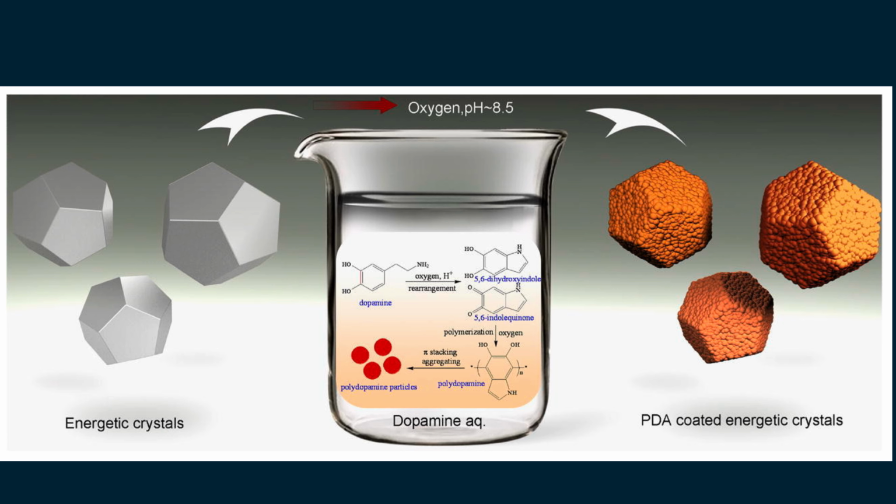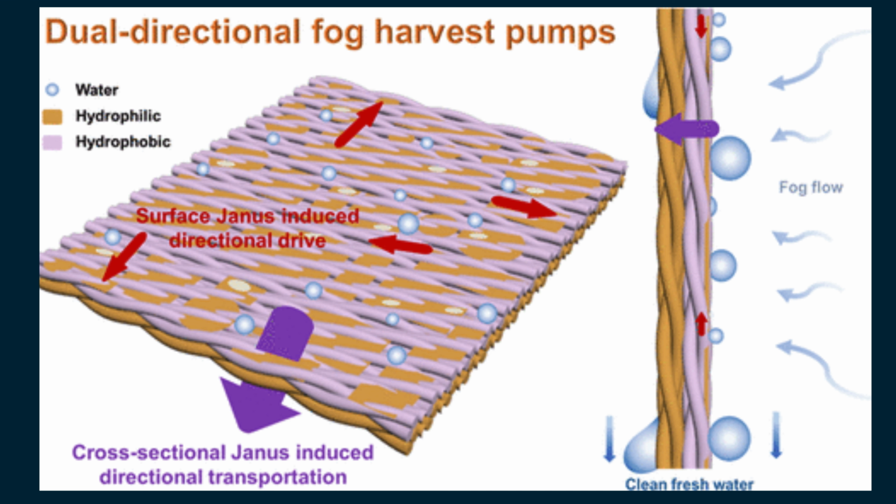Polycatecholamine surface layers. Polycatecholamines, particularly polydopamine, PDA, are widely used as adhesive interlayers for surface modification. Dopamine hydrochloride undergoes oxidative self-polymerization in alkaline solutions, e.g., tris-HCl buffer, to form PDA coatings. These coatings can create a hydrophilic surface, while the opposite side may be modified with hydrophobic molecules such as perfluorinated thiols or alkyl silanes. Polymer matrices and functional additives. Other polymer matrices commonly used in Janus foams include polyurethane, PU, polystyrene, PS, and polyvinyl chloride, PVC. Additives may include silica-based Janus nanoparticles as compatibilizers or nucleating agents, and lithium chloride to create hygroscopic regions for moisture-assisted cooling.